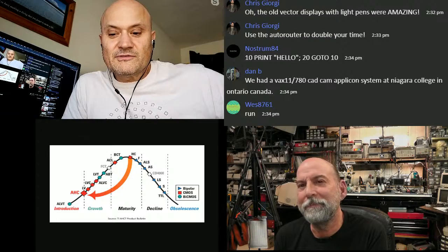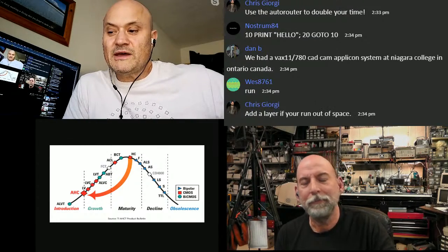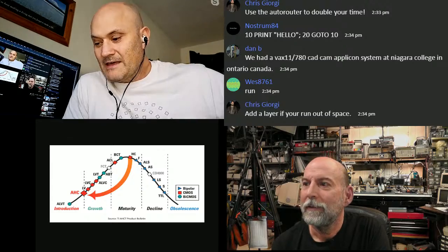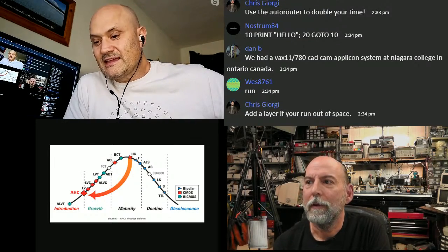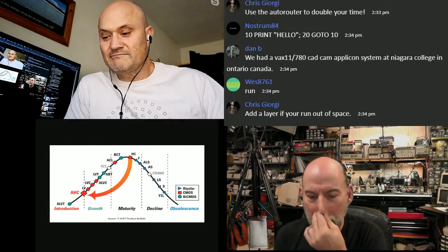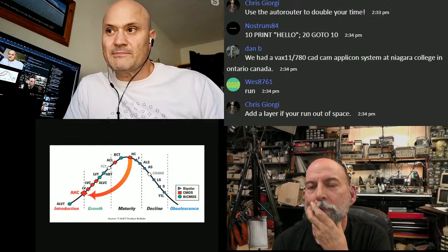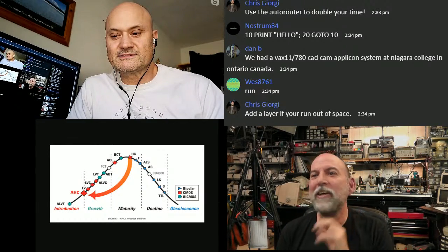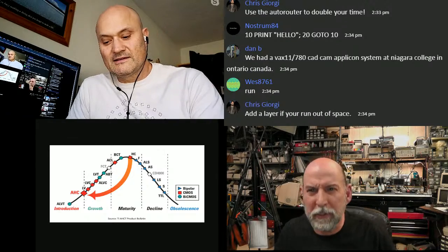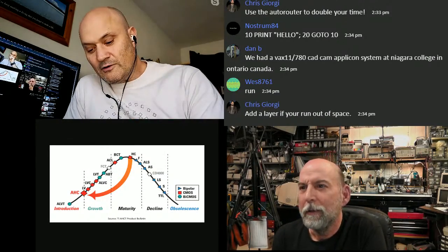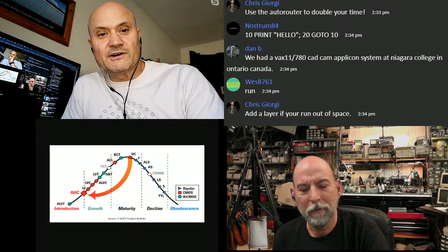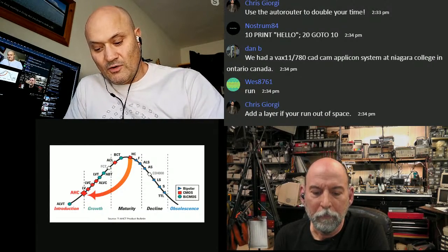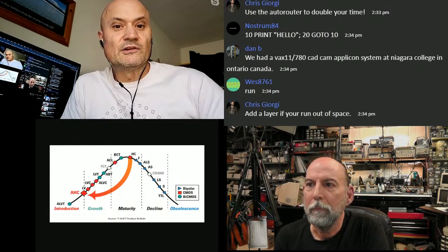There's 2 reasons for that. One is they get a new CAD package. It's got an auto router, because they all do these days, right? They load a design, they get all their parts placed, and they do the basic rectangle board shape, and they click route, and it does a crap job because it doesn't know about channels and buses, and they've spent almost no time setting it up, right? Right. Or they just don't like the look of the results.